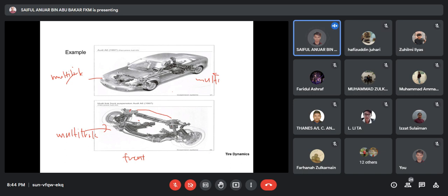Okay, you need to remember that sometimes for high-end cars, Japanese, continental cars like BMW and Mercedes, they don't use a common suspension configuration like our national cars. Usually, for us, if we use McPherson strut for the front suspension, we might be using the common trailing suspension at the back. Okay, that's for common price vehicles. But for high-end vehicles, they can have multi-link at the front and also multi-link at the rear.